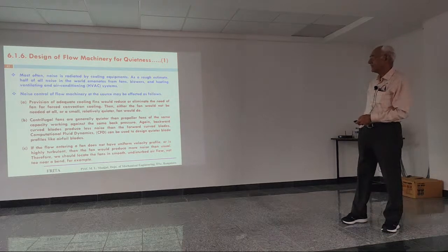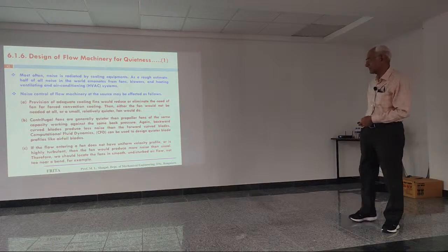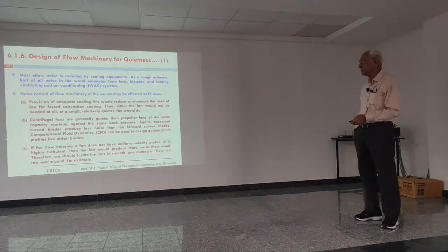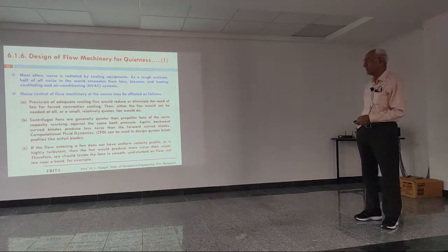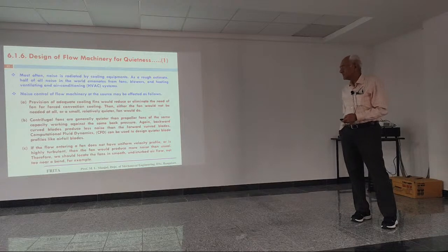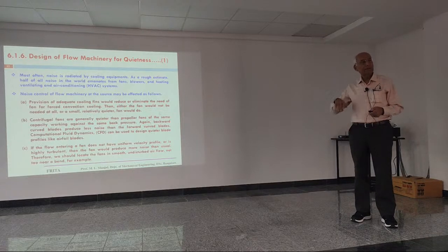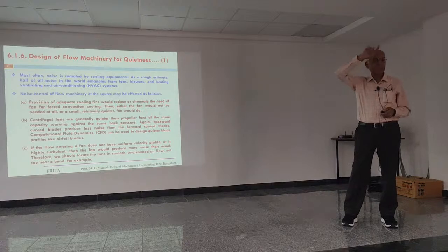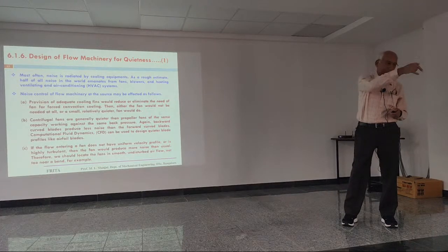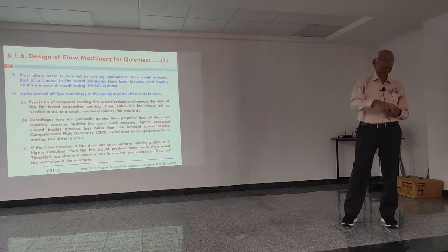Now, centrifugal fans are generally quieter than propeller fans of the same capacity, working against the same backpressure. Again, backward curved blades produce less noise than forward curved blades. And computational fluid dynamics can be used to design quieter blade profiles like airfoil curved blades. So what I am trying to say here is that noise can be reduced if the flow machinery is designed properly.